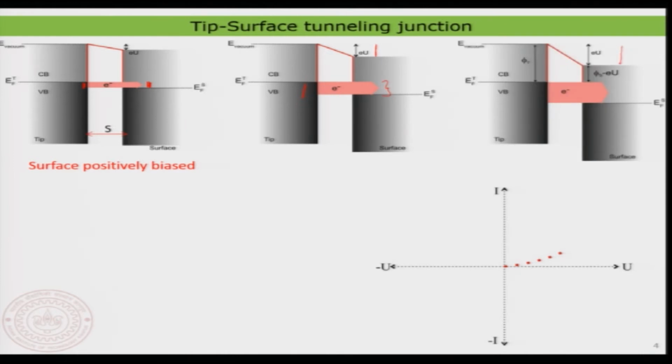So, that is what is basically indicated by this: the voltage is increased, and then you clearly see that I have started tunneling a lot of electrons from the tip to the surface. Obviously that is quite interesting. Now you see that the tunneling current is rapidly increasing as the voltage increases. But strikingly, there is something quite different in this case compared to your ohmic contact. It is no longer looking linear, as in the case of ohmic contact.